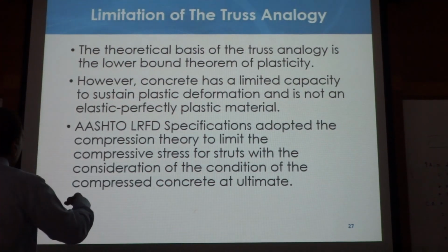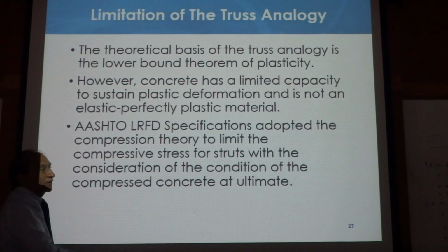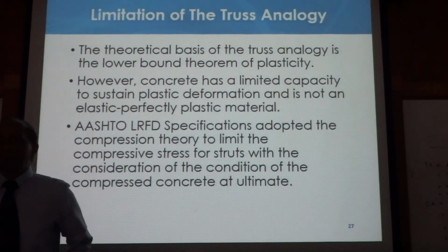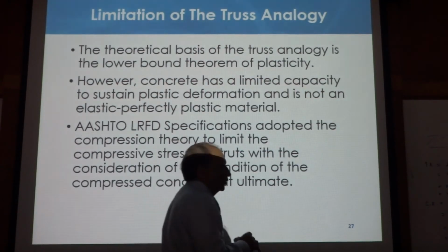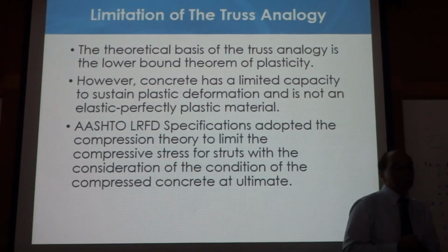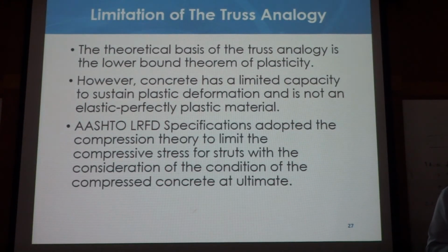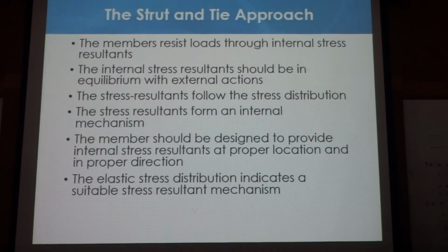So that is one of the ways to control or overcome the shortcomings of the Strut and tie model: you calculate the forces, and after this you say, okay, concrete cannot take more than this. Because concrete cannot take more than this, then because of equilibrium, steel also cannot take more than a certain amount. Okay. I know many things are not making sense to you right now. When we go to actual applications, we will understand these concepts again.